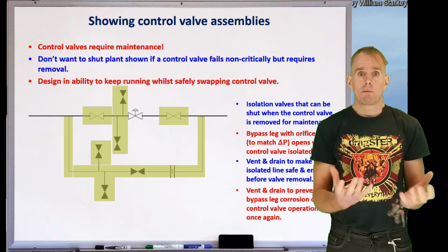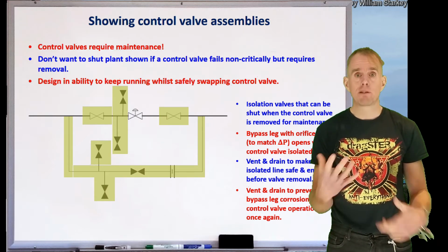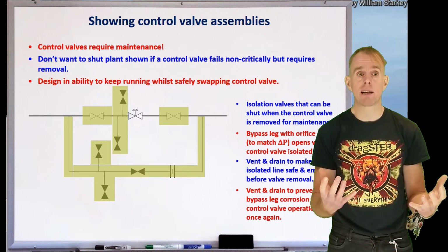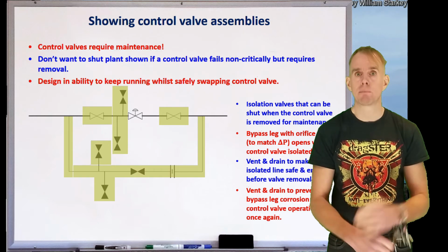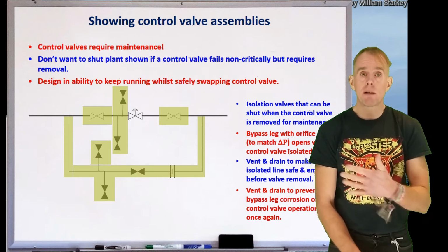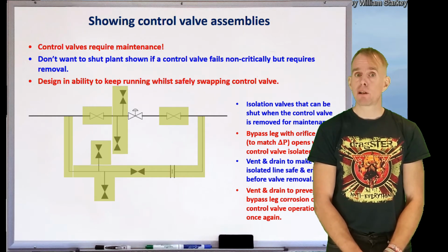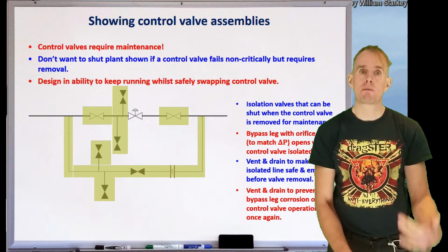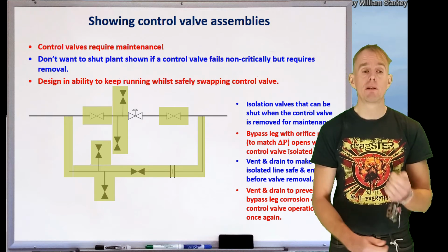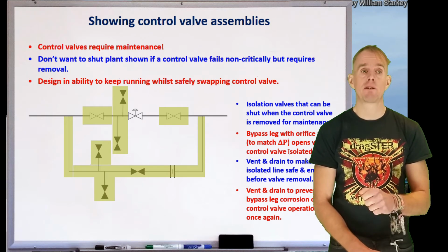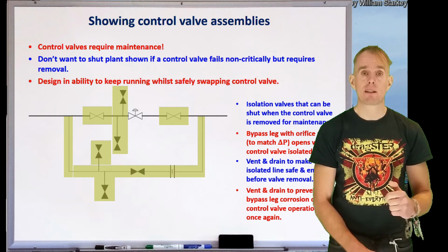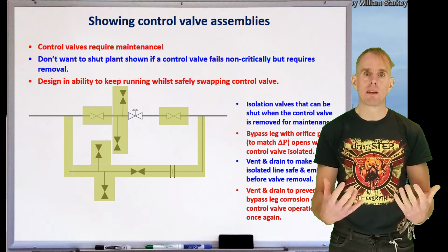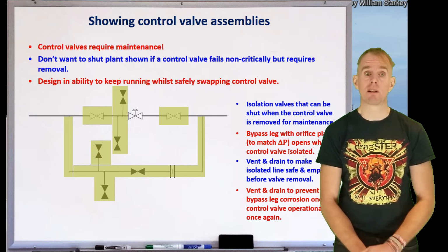Basically, you don't want fluid just sitting in a bypass leg. If it's a corrosive fluid, over time it will just simply eat away at the valve seats, it will eat away at the pipe walls, and potentially, if that bypass leg isn't used for a decade, you could have had a decade's worth of corrosion happen before it's put into use. It's suddenly put into use, pressurised, and the whole thing fails. And so you want to make sure that the bypass equipment is in good, safe condition for use, and it doesn't exist sitting with a liquid in there for sometimes months or even years at an end.